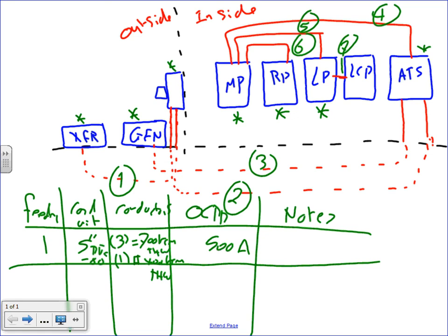In Revit, you can have them all in one. So you're going to have the feeder number, the conduit, the conductors, the overcurrent protection device, and some notes. What Revit allows you to do is have the number of conductors in one column, the size in a different column, the insulation in a third column. That's up to you. I mean, minimum when you draft it, this information any way, shape, or form.